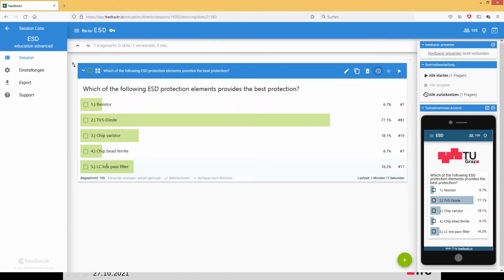So usually now we are making the look and feel experience. So a volunteer can now press the finger onto these different protection structures, and depending on the reaction of the participant, you can then really see how good or how bad the ESD protection is. And as you already have figured out, the resistor is not that effective as an ESD protection structure.